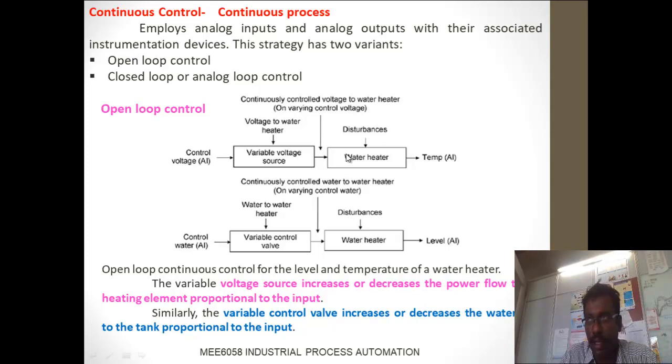the water heater. The process is the same, but here the on or off controller is proposed in a discrete process, whereas in a control process having limits, that's a continuous process. For example, 0 to 5 volts. So 0 to 5 volts indicates to switch on or switch off the process. In that 0 to 5 volts, we can categorize like that: 0 to 2.5 volts is taken care of to switch on the water heater, then 2.6 to 5 volts is taken care of to switch off the water heater. As like that we can categorize.